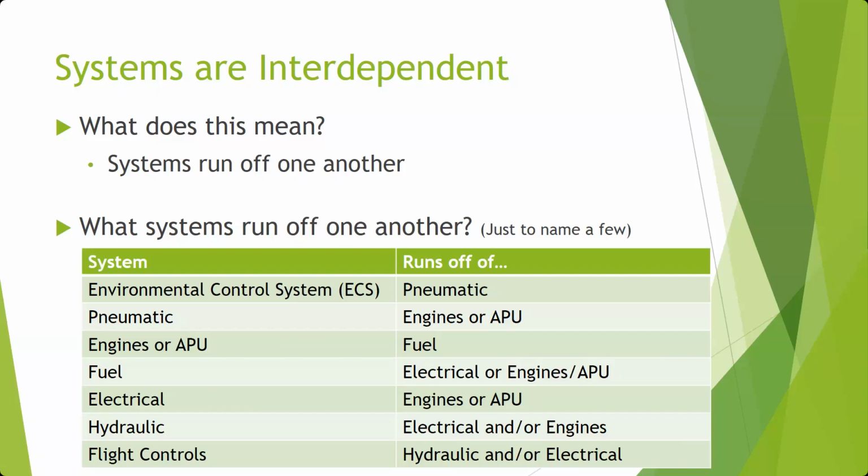Now hopefully whoever's working in that area has gone and pulled the circuit breakers for hydraulics and put little red or yellow clips on them to prevent somebody from doing that. Or put a little sign, usually you do multiple things, on the hydraulic system switches so that someone doesn't turn them on. Okay? You've got to think about it from both ends.